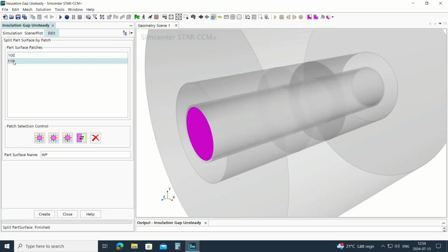And we have the lateral direction, and as we discussed, we don't assume the heat transfer to happen along the length of the water column. Okay, this is an assumption because you have almost similar temperature on the lateral faces, so a temperature gradient is nearly absent, and we can consider it as an adiabatic condition. Okay, so this can be W5.